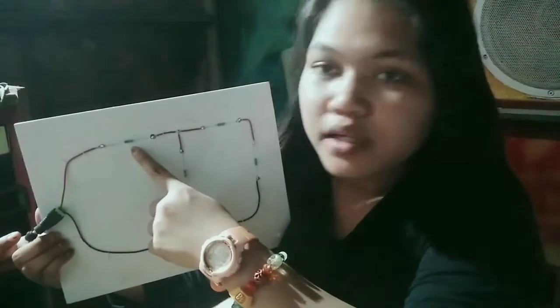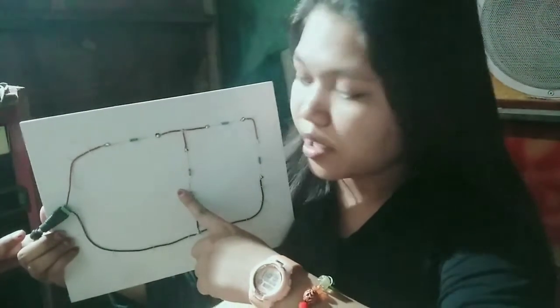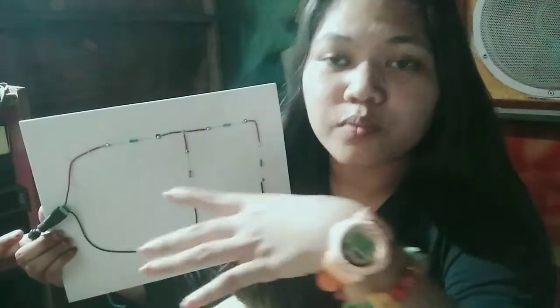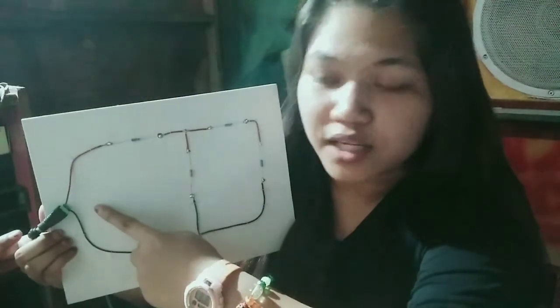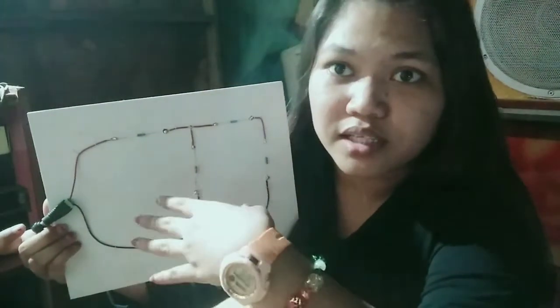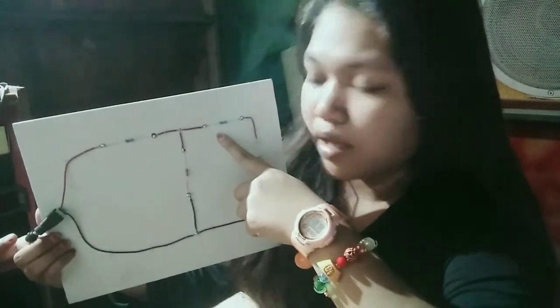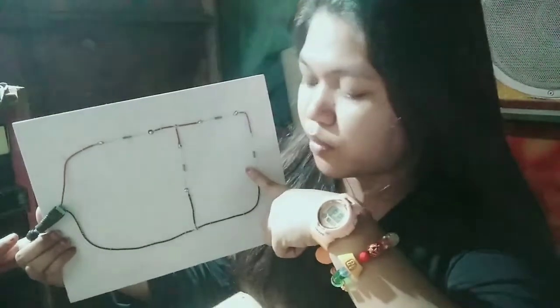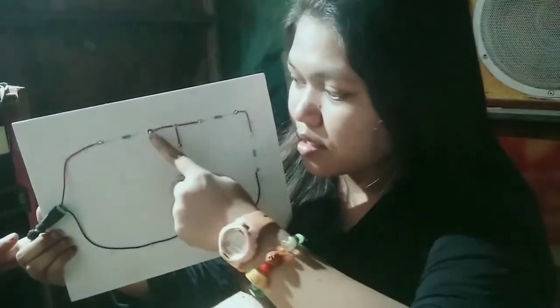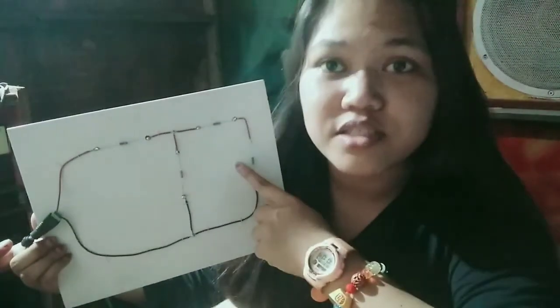So if we have a voltage of negative 10 here and a voltage of negative 9 here, and we add those, it would result in negative 19, and our source here would be positive 19, so 19 minus 19 would be 0. The same at this point. If we have negative 5 here and approximately negative 5 here, if we add these, we will have negative 10. And since it has a resistor, our source here would be 10 volts. So 10 minus 10, we will have 0.